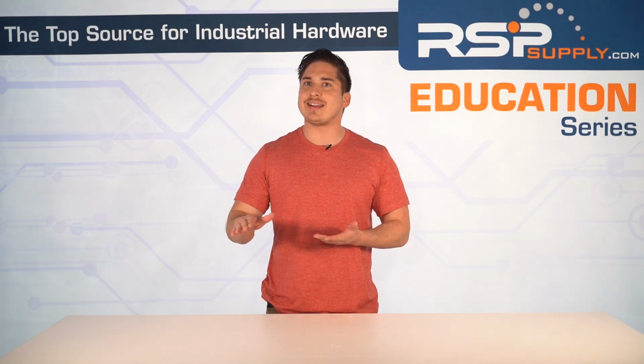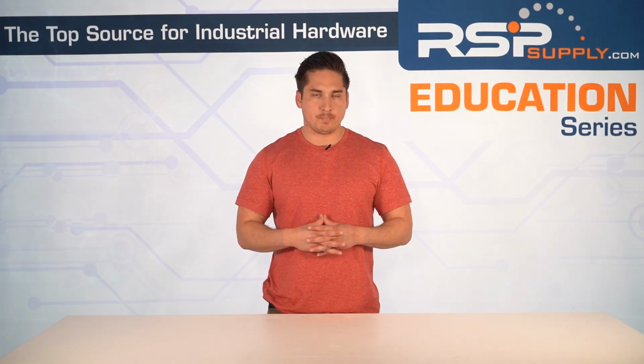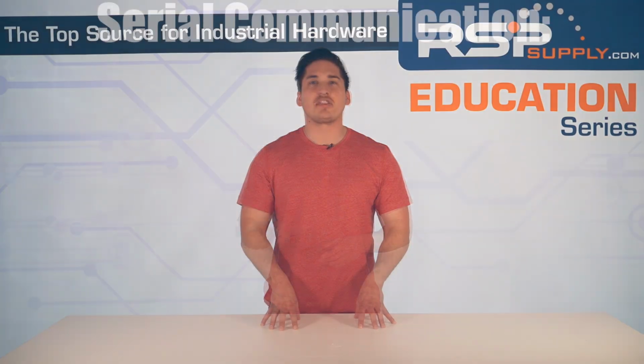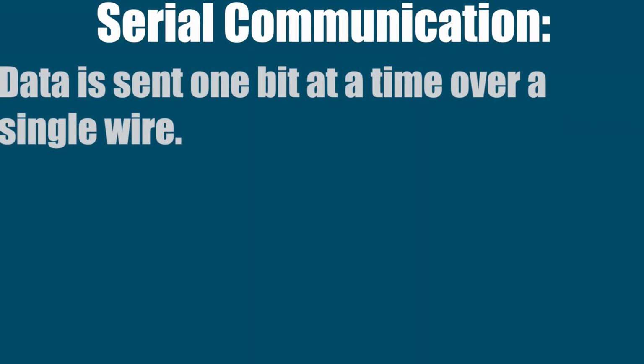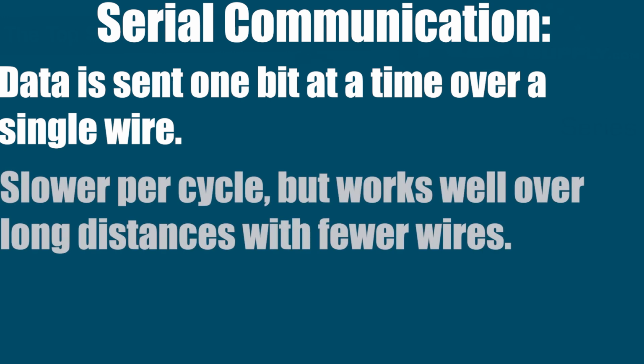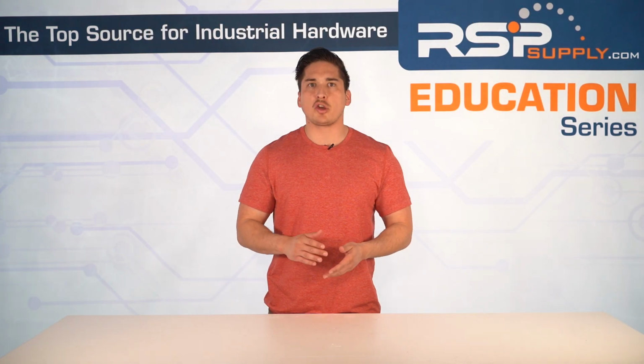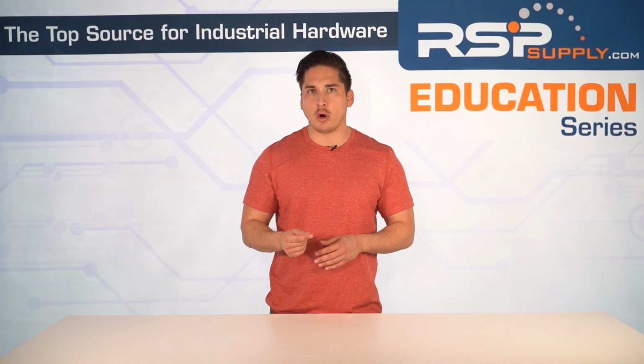When we talk about sending data, there's two main ways to do it. There's serial communication and then there's parallel communication. So for serial communication, data is sent one bit at a time over a single wire. It is slower per cycle, but it works very well over long distances with fewer wires, just one. It's very common in industrial automation. It runs with RS-232, RS-485, Modbus, CAN bus. Think of it like cars going one after another on a single lane road.